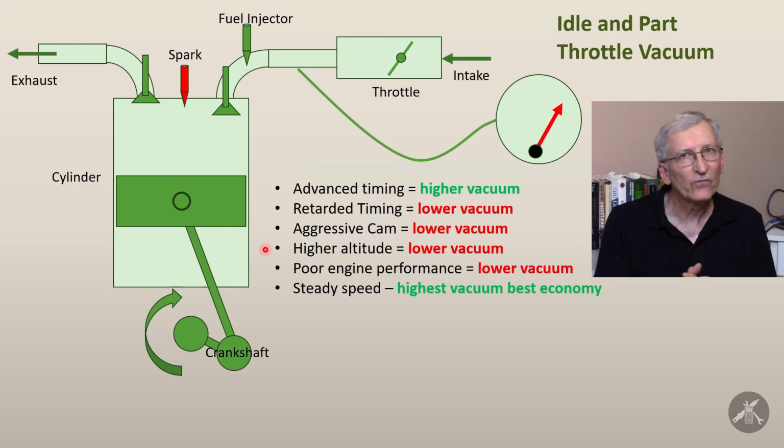Back when I was first starting out in this business, we were working in brakes, and we had power brake boosters on 4-cylinder engines in the Rocky Mountains at high altitude, and we were having trouble getting enough vacuum to make them work right. It took some different things to get that vacuum up, or to get a powerful enough brake booster to work with the lower vacuum.